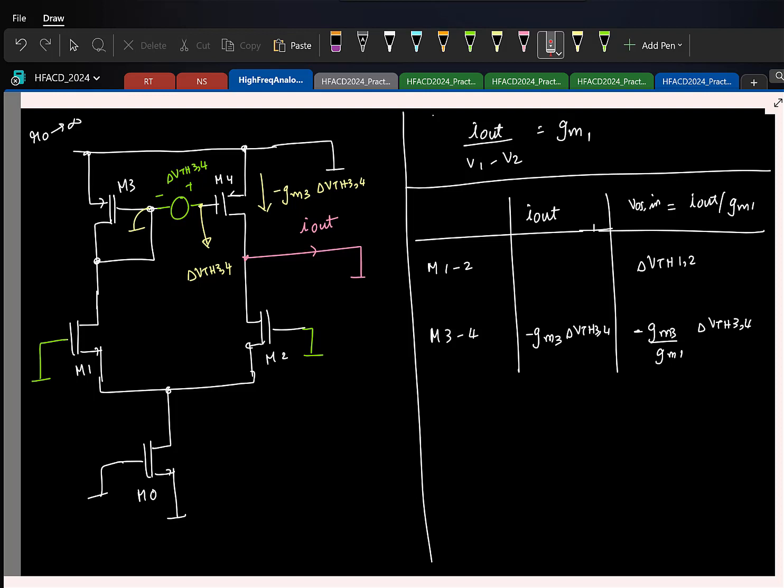What you are saying is that the properties of this transistor can change compared to what we decided. That is basically the process variation. Now mismatch is basically between two identical devices. Here also the property of this one will change from that one, but that violates your assumption that the GMs of these two transistors were equal.